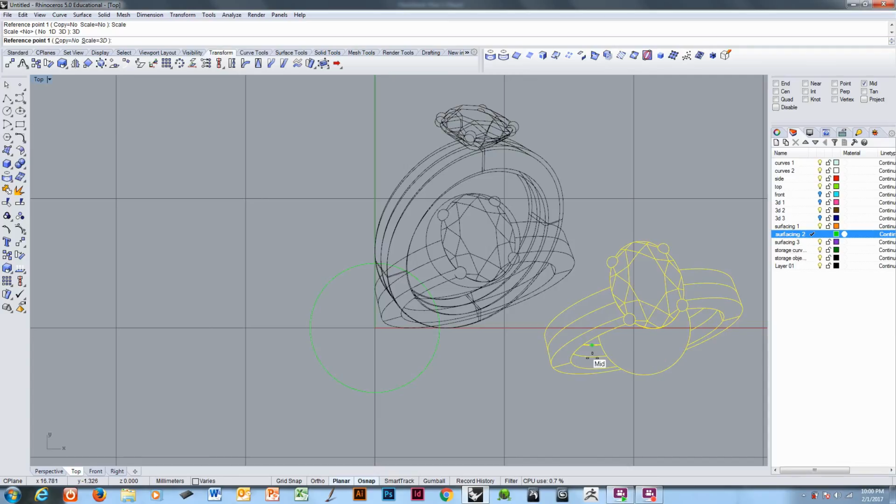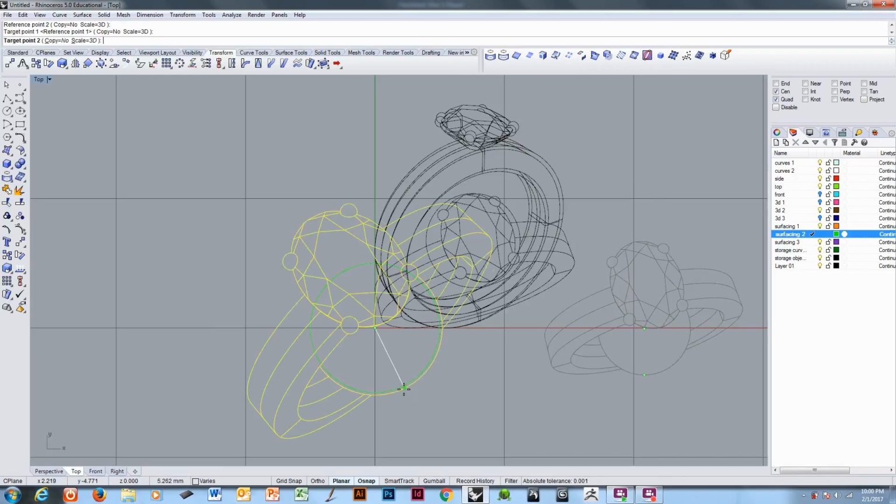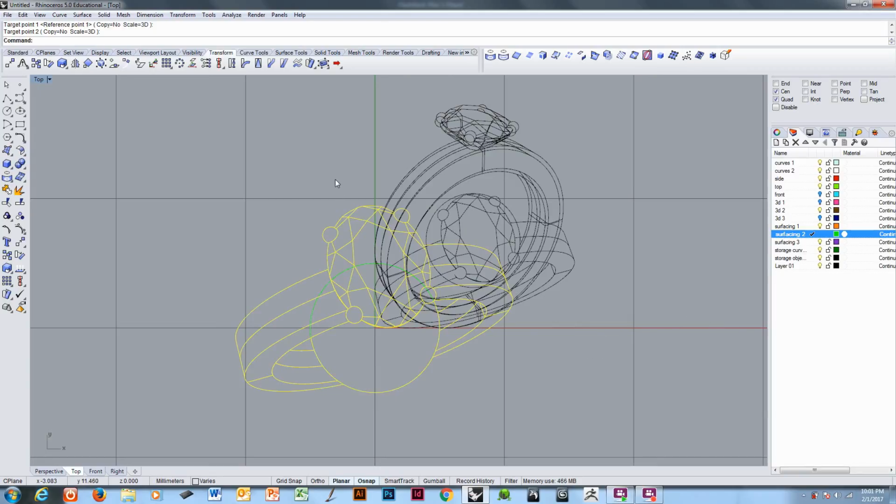We're going to be using this circle as our pick points, as our reference. So obviously I can see a whole circle here. I can only see a piece of a circle here. To make it work, I'm going to need to use 2 snaps, a center and a quad. To get the center of that circle, if I touch anywhere along its edge, its circumference, I will get a center point. Click. The second pick point, reference number 2, will be a quad. Target number 1 will be center again. And target number 2 is quad. And now this drawing is actual size.